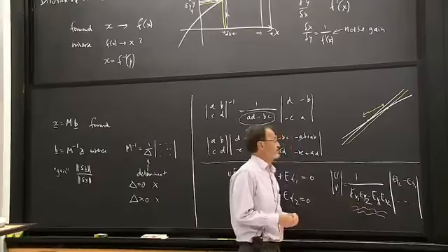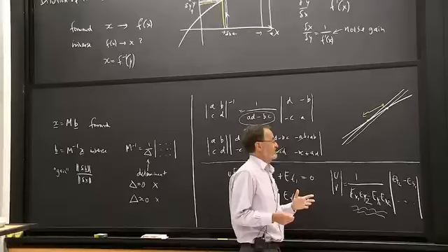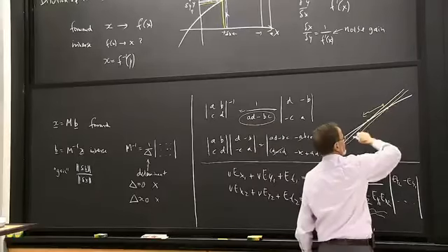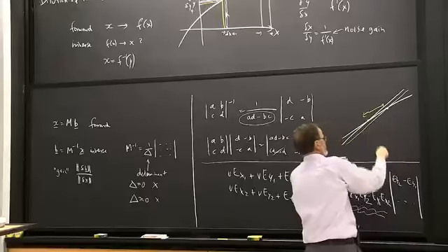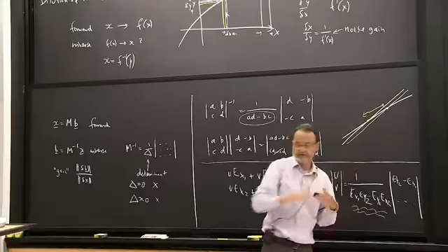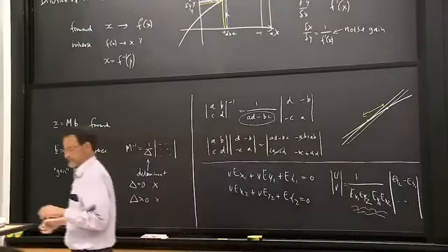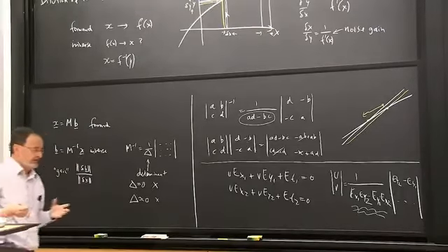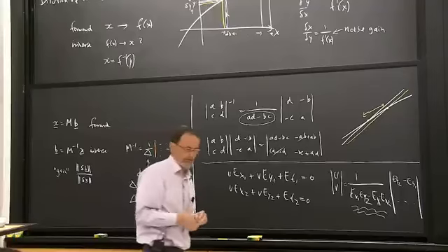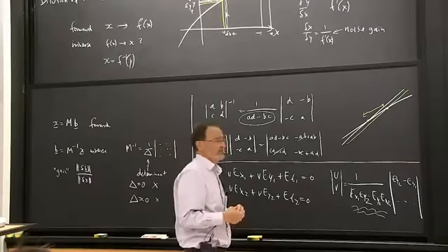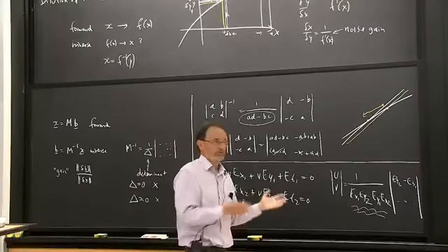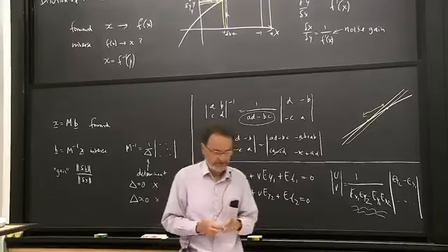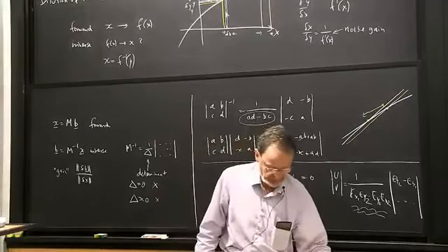Notice that not all hope is lost. It's true that the component in this direction we don't really know very well, but we got very good constraint in that direction. So that's another lesson, which is, we may have a situation where the noise gain is high, but it may not be equally high in all directions, as we saw in the diagrams I showed you. And it's good to know which component you can trust. If I'm going to have my robot move over and pick up a part, that's a useful thing to know.